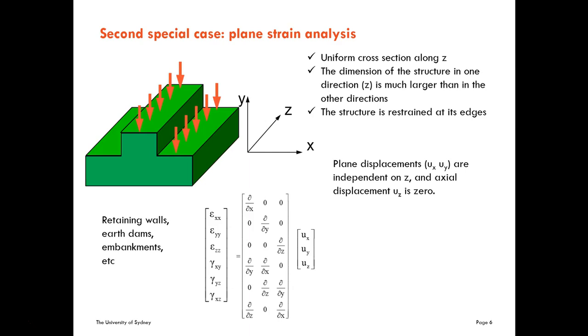So let's go to the equations that we use to calculate the components of the strain in terms of the displacements. So this one is going to be 0, and these two will depend on x and y only. So let's see. We are going to have εxx different from 0 because it's the derivative of ux with respect to x.